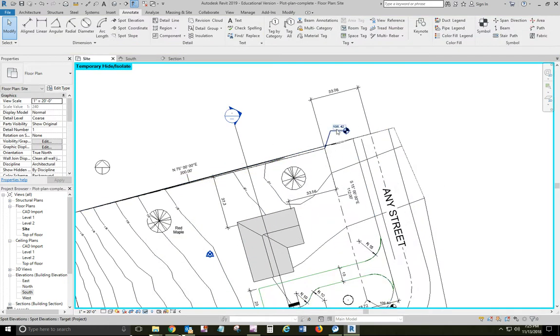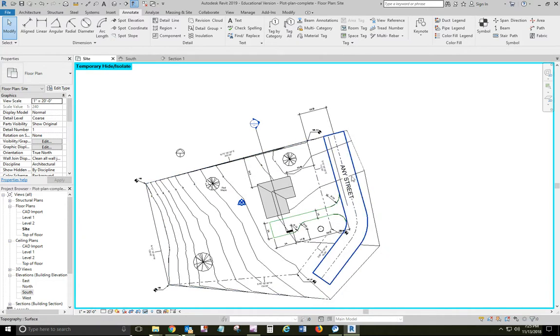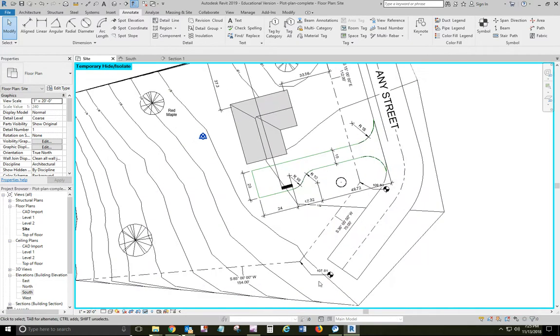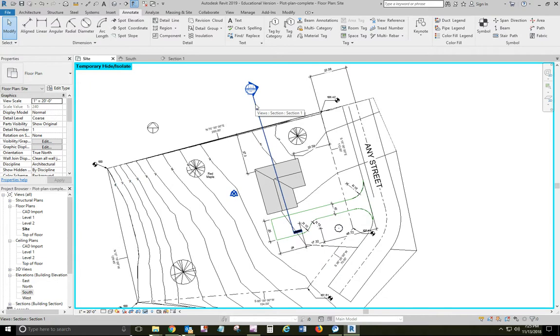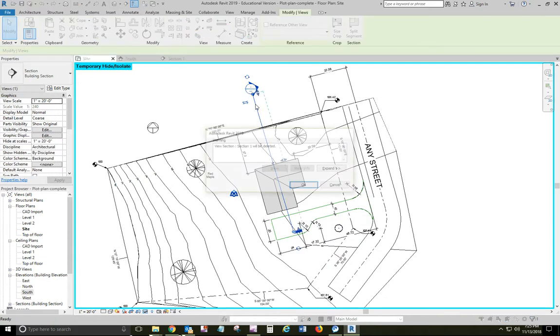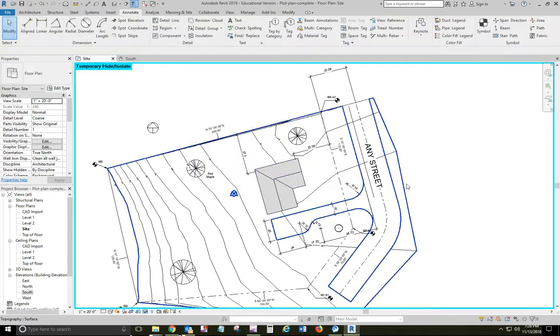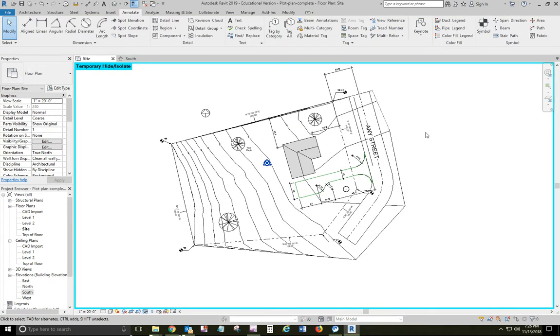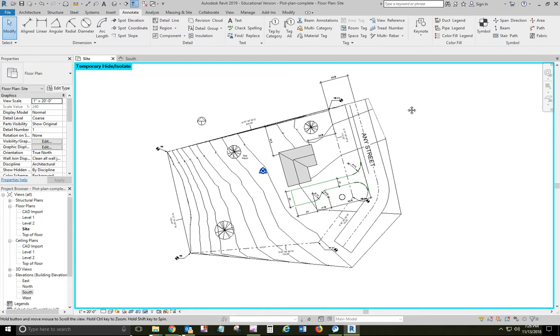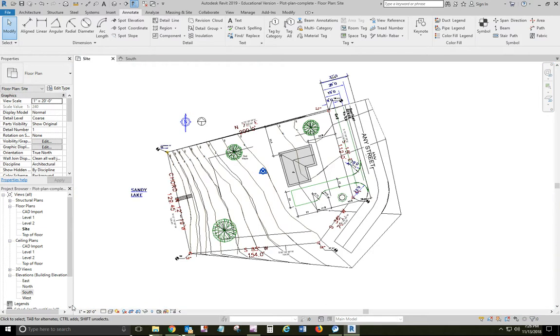Okay. You'll have to move this elevation marker over. You may have to clean up some stuff, do some moving around of some of your annotations and dimensions. You just kind of slide them a little bit. Okay. We don't need the section view after you're done with that. So you don't need it after you're done with it. Now, when you save this file, it's going to save the house and the drawing also. So it kind of does double duty on the thing. I'm going to reset that.